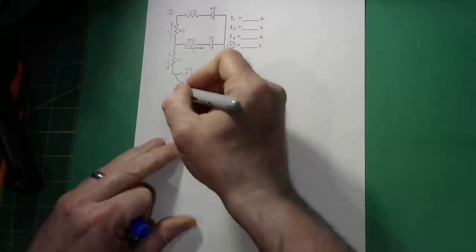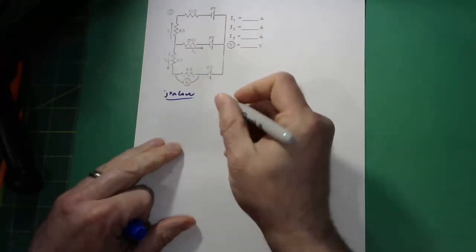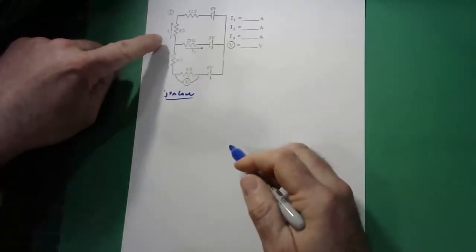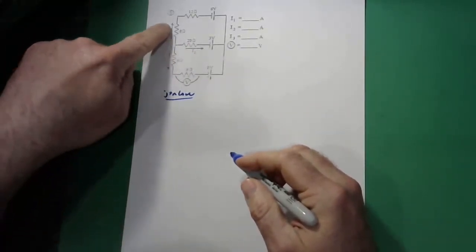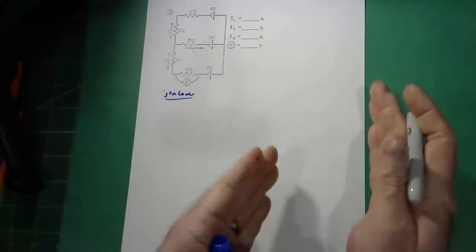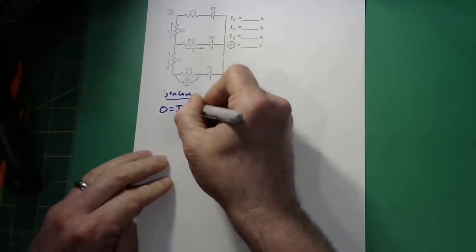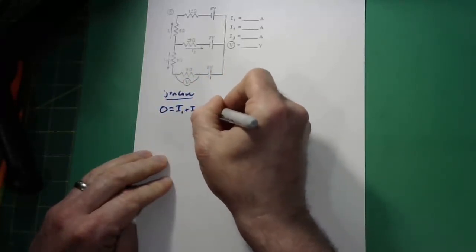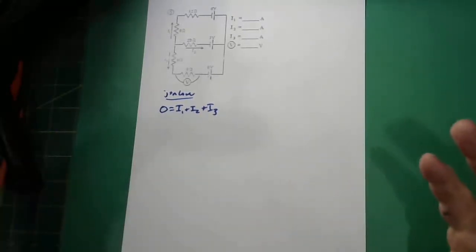Okay, so let's start up. Let's go ahead and get our junction law. I'm going to choose to use this left junction. Notice they've got the 3 currents labeled for you. And you say, now, wait a minute. All these currents are going away from the junction. So if I do sum of the currents in equals sum of the currents out, I would have 0 going in equals I1 plus I2 plus I3 exiting, going out of that junction.